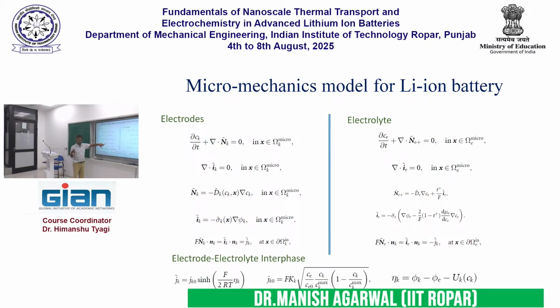Electric potential you know, the amount of work required to bring a unit charge. Now these four are the electrolyte equations: the conservation of the lithium plus ion, the conservation of charge, the constitutive law relating the flux of the positive ion with the concentration gradient as well as the current, and the current again related with the potential gradient as well as the concentration gradient.